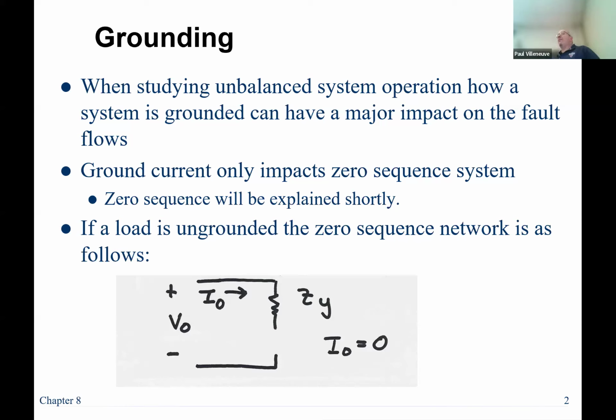If you ground a system and then someplace else on the system, a wire comes into contact with ground, then you get a current flowing through ground. What if you're the person that touches that wire and connects to ground? Is that a good thing or a bad thing? Bad for you, yeah, really bad for you. So do you think having a system that's grounded is a good thing or bad thing? Based on that one circumstance, it might be bad, but it's actually a good thing.